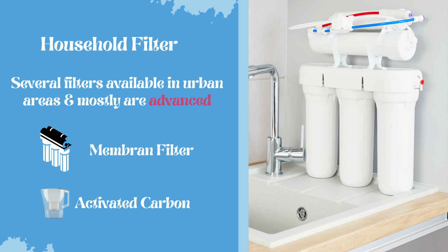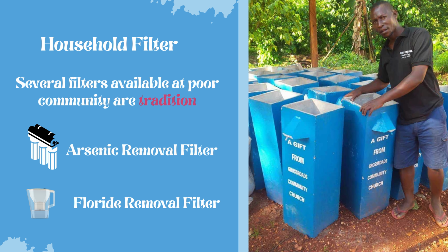Let's address the household filters. For urban settings, most households rely on advanced membrane technologies like ultrafiltration membrane filters and activated carbon filters. Regarding poor communities, they rely on traditional filters like arsenic and fluoride removal systems, or using a simple small-scale rapid sand filtration called biosand filtration. All these methods offer essential solutions for clean water access.